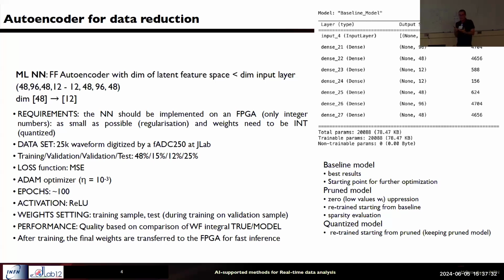The number of weights we use should be limited, because an FPGA is not like the computer you are using; it has a dedicated RAM that usually is not as big as the one you have on a computer. On top of that, you have so many channels to be connected to the input of an FPGA that you want to save the RAM. So again, there is a need to reduce the size of your network.